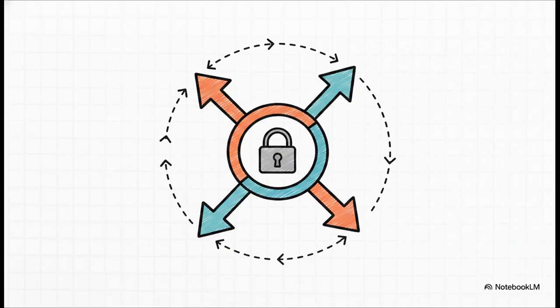Now, why do we use these phasors? Honestly, because they take absolutely nightmarish complex math and make it incredibly simple. If you have two different currents with the same frequency, they might not hit their peak at the exact same time, right? They have what we call a phase difference. But because these phasors rotate at the exact same angular velocity, that phase difference stays perfectly constant. We can lock it right in place and evaluate it.